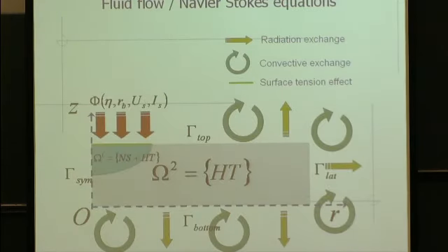So basically, I will summarize quickly the model we have stated. On the top, you have this heat flux obeying a Gaussian distribution. Yes, I forgot to start with the domain, as I said, where we solve the Navier-Stokes equation and the heat transfer problem, and the solid one, where we solve only the heat transfer problem. Then we apply, in the heat transfer problem, this load or heat flux on the surface. We have some boundary conditions around for the heat transfer, both convective and radiative, so some heat loss.